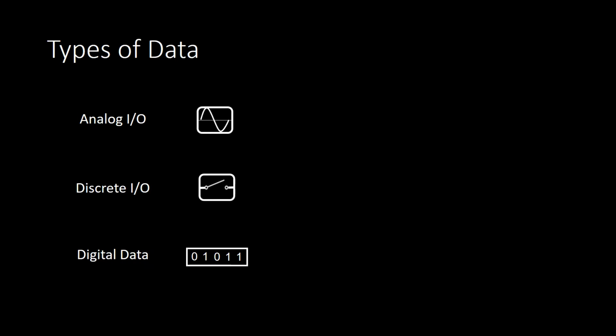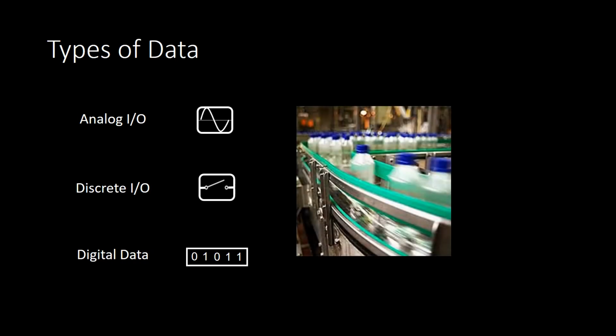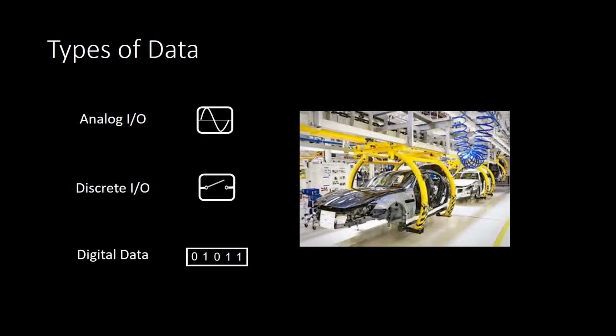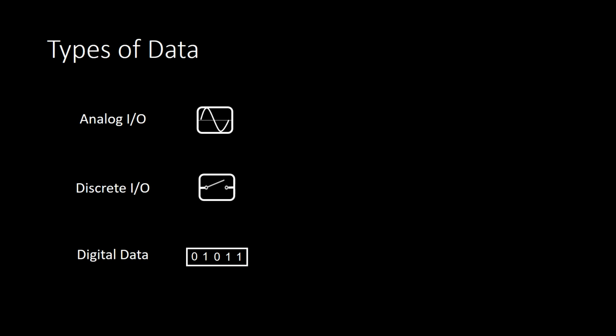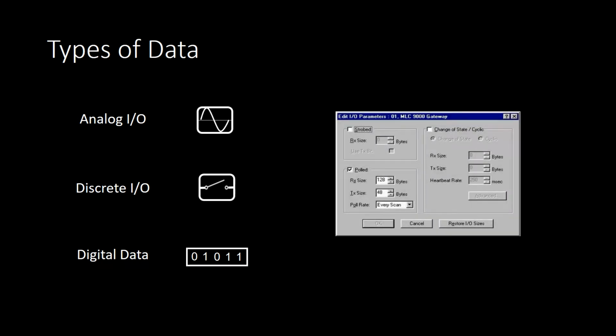I/O messages are set at dedicated speeds and will have priority over routable client-server data. This makes them more suitable to high-speed, repeatable communication at device level. DeviceNet is an example of I/O communication which can be configured to a set speed and polling arrangement.